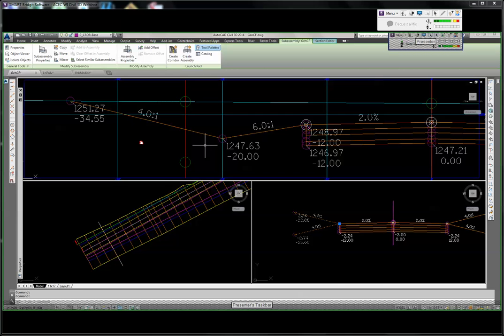What's going to happen is when I target that, this slope will continue on at 6 to 1. I believe there's actually a point where it gets to the rollover point, and we'll get to a 4 to 1 portion. But basically, the ditch bottom will end up at the elevation of the profile. Not necessarily the alignment location, but the profile elevation, using the slope to get there. Then at that point, it takes a left-hand turn and goes back up to daylight, as we would expect.